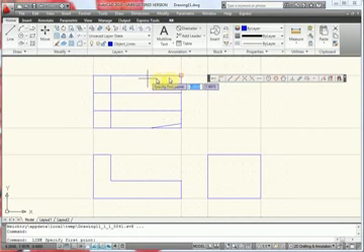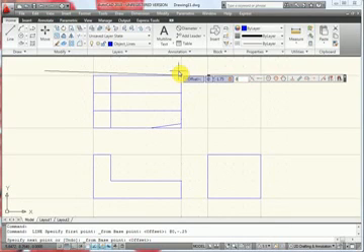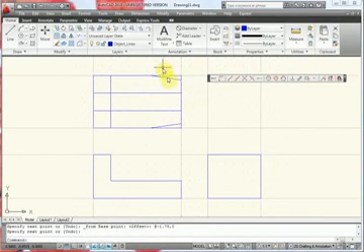And I'm going to do the exact same thing on the top here, but my relative coordinates are going to be a little different. So I'm going to use the Snap From tool, choose my Snap From point, I'm going to enter a coordinate of at 0, -0.25. I'm going to use the Snap From tool one more time, and I'm going to enter a distance of at -1.75, comma 0. When I'm finished, I'll press the spacebar.